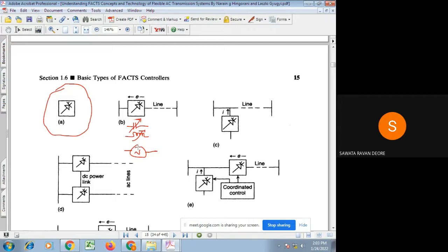That is, we call second order, third order, fourth order. That is, by that time it is of fundamental frequency, that component is there. Whereas subsynchronous means less than the fundamental frequency. If that unwanted component, rather than the fundamental component present in the source voltage, is less than the fundamental frequency, it may be a 2 hertz component, maybe 5 hertz, 10 hertz, 15 hertz, 20 hertz, 25 hertz, 30, maybe up to 49 hertz. So if a component less than the fundamental frequency is there, then it is called a subsynchronous component.